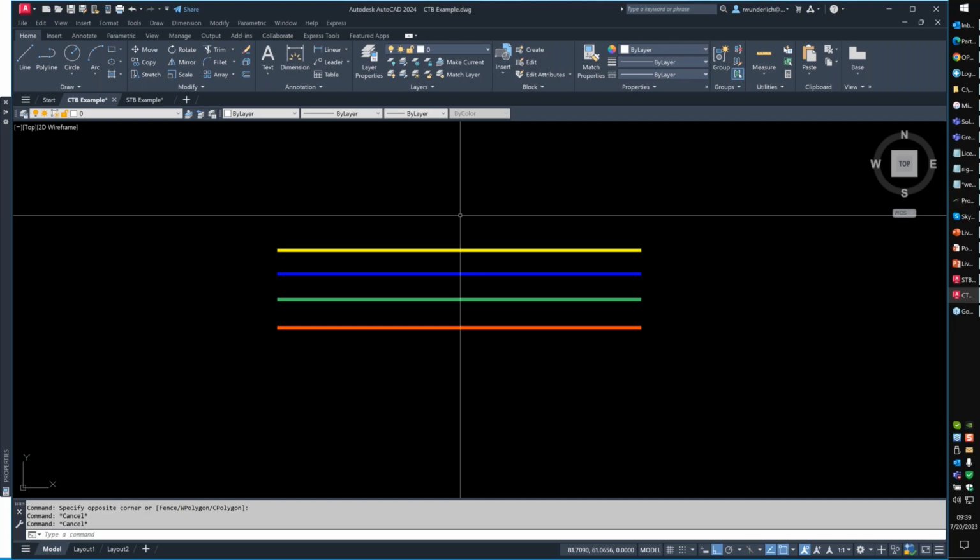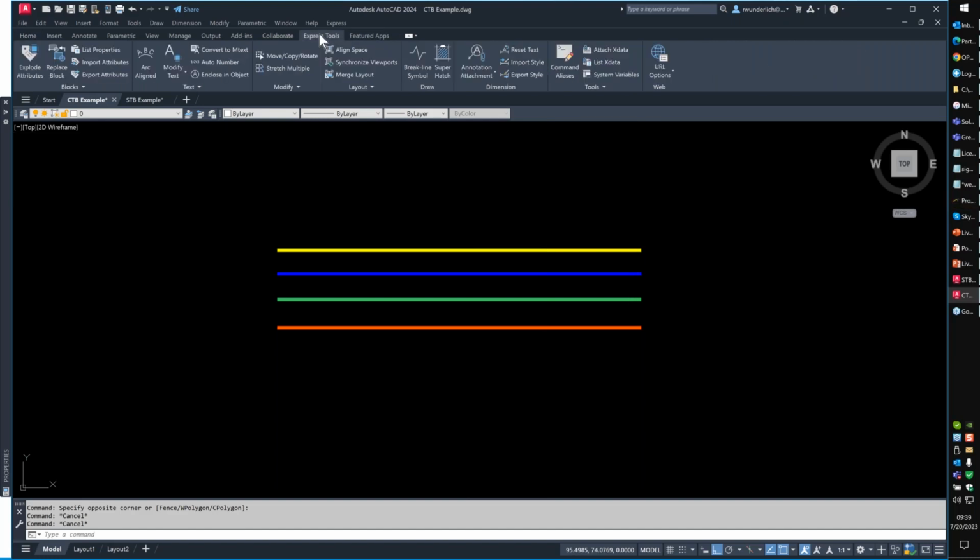Is there any way to strip out a lot of unneeded lines from an imported drawing? There's a couple of things. I personally like Overkill, which will try to strip out a lot of that. That's one option. There are other options, like a couple of Lisp routines I have that do a little more aggressive cleaning. The other thing I like to do is use QSelect and try to select things that are concurrent, or get rid of things that are very small. If I'm dealing with a large drawing and I see every screw, nut, and bolt, I'll get rid of everything with an arc radius of 1/4 of an inch, because you'll never see that on a drawing, to help clean some of that up. But that's more of a process flow, but it can be done.